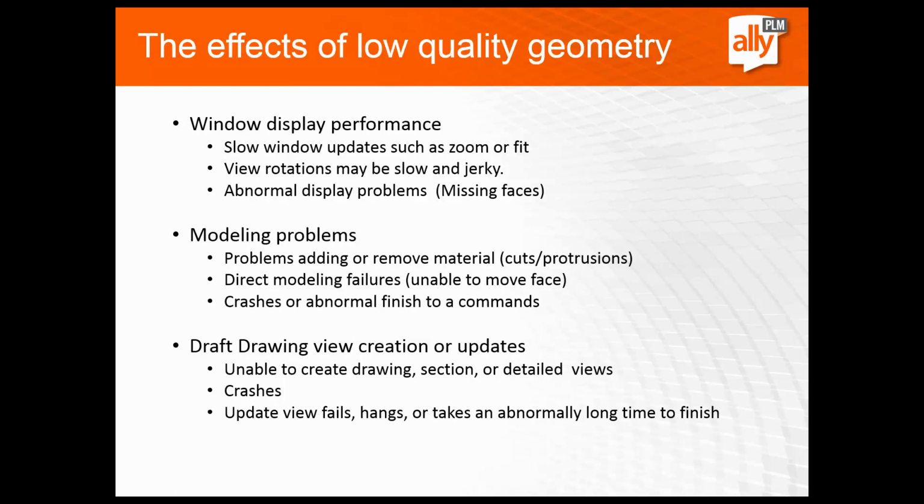So first thing we're going to talk about is the effects of some low quality geometry. You've probably dealt with this before if you've ever imported files: some Windows display performance issues. What it really does is it slows down our Windows updates such as zoom or fit. Rotating the model can be slow or jerky at times, and you also may have some abnormal display problems such as missing faces.